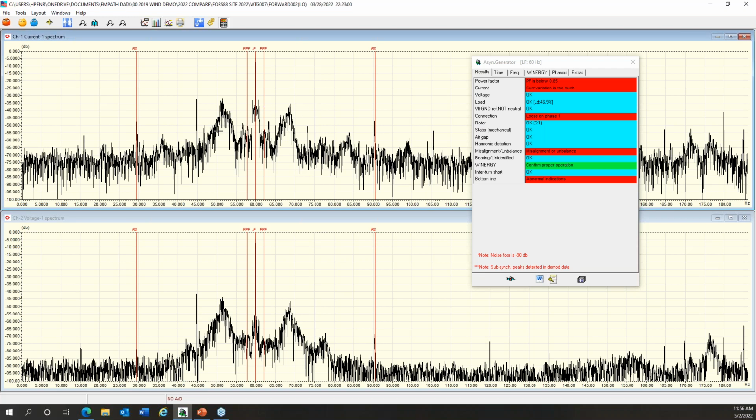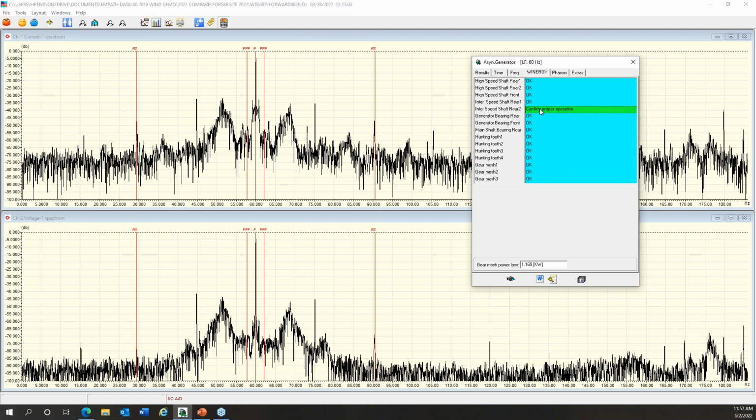Now with a Suzlon, these peaks always show up. Those relate to the gearbox. I always see them. Really not much. We've attempted all kinds of stuff with one of the companies, wanted to see if they could improve on their gearbox. So we know that if we see these, they're there. We do know that there's other peaks that tell us when something is going wrong. So unlike when I show you what a GE looks like, this is very unique to Suzlon's. So we just accept that as a signature. Now the one-time RPM, these other peaks are, by the way, other things going on, such as this.